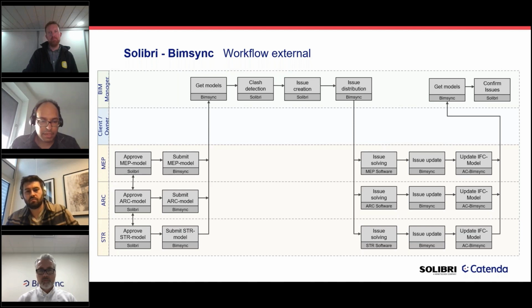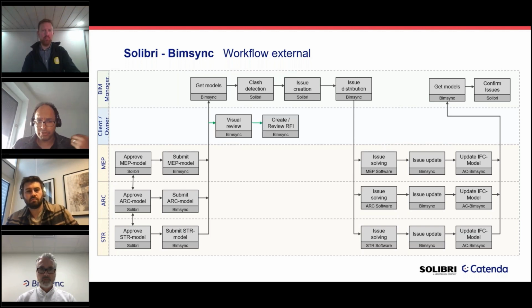So here the client can access the models, federate them, view them how you want to view them on Bimsync, because all the engineers are uploading their models on Bimsync anyway. He could create and review RFIs that are sent to him, or create RFIs himself.